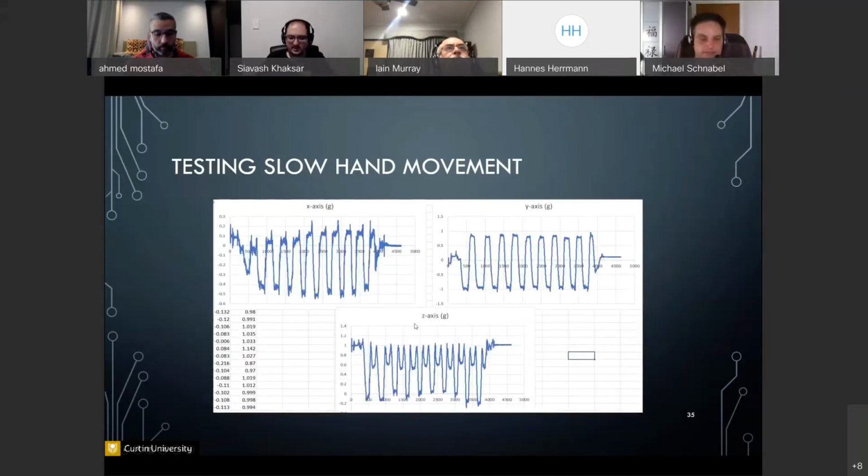Now, here, especially on the z-axis, and as I said, this is before the data was processed, and this is from a commercial sensor, not the ones I showed you. As you can see, it has drifted down a lot. So this is a very good point in showing you why it's important to look at those signal conditioning steps once you have all of your setup, just to make sure the data you're getting is not being drifted like this. This is something that we can always fix in post, and then once we have that fix in place, hopefully by having a more powerful processor, we can start doing some of that pre-processing while we're capturing the data, so we don't have to fix it as much in a post-processing implementation.